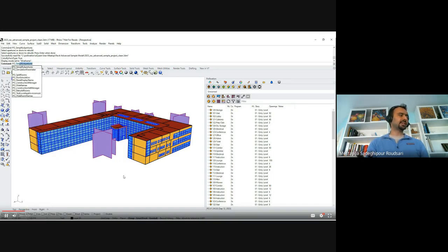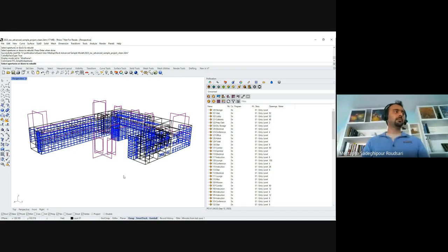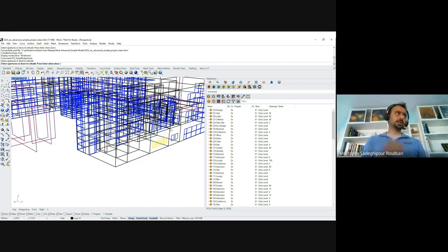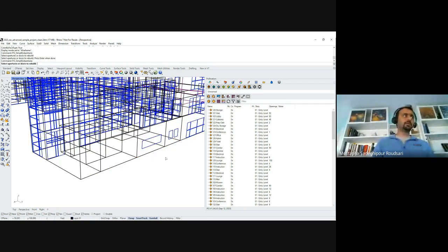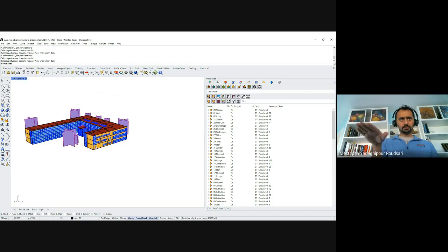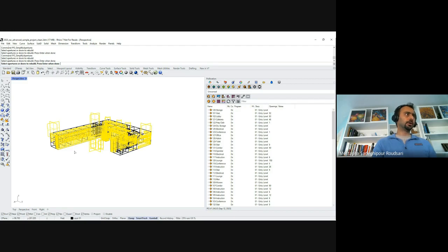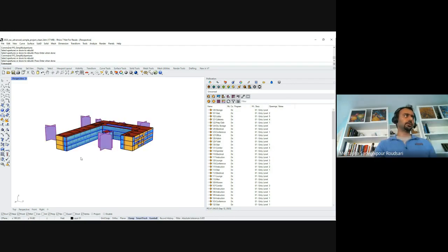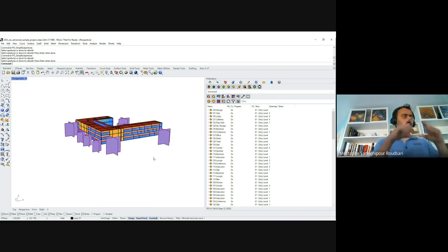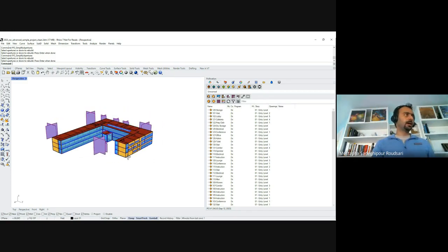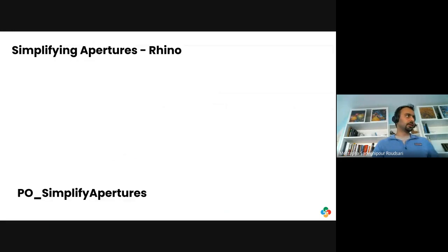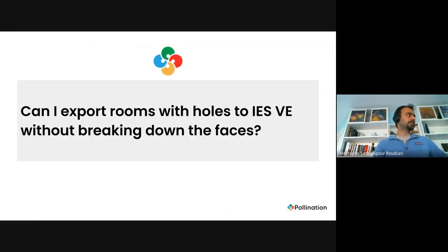This is a recent command. In Rhino, you have more flexibility, so you can just select the ones that you want. In Revit, it's per floor, or per level. But of course, in Rhino, you can also select everything, and it will work. And it's a little bit different how it positions in Rhino. Rhino calculates the average of the input. In Revit, it just puts it in the center of the face. They're both good.